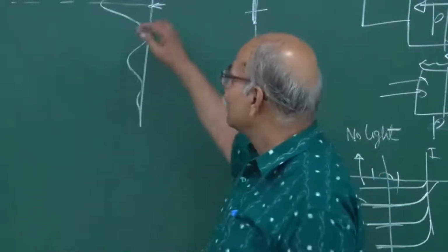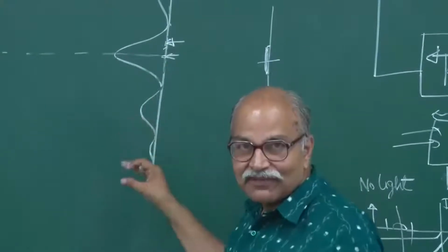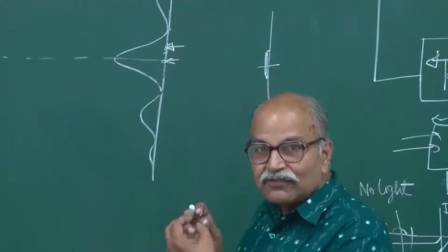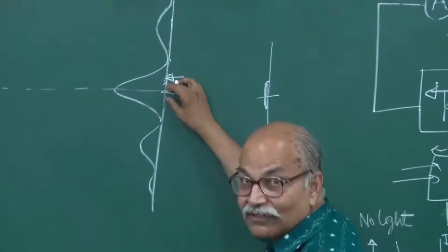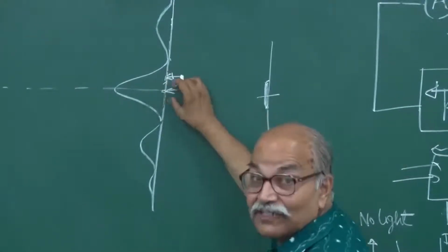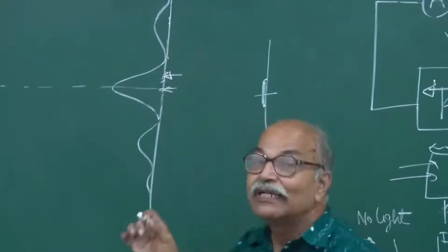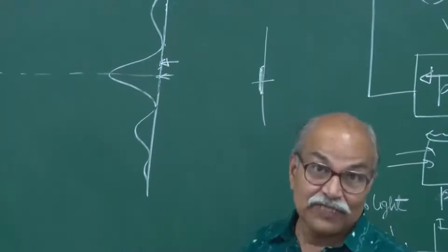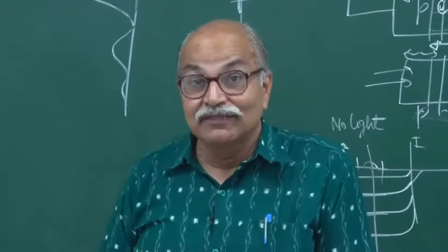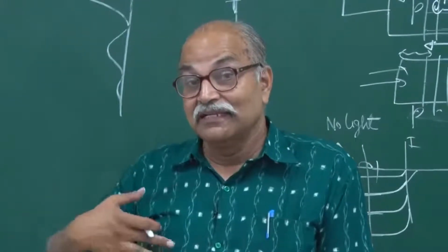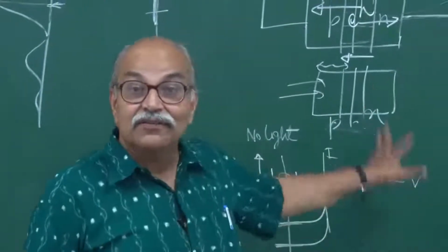Okay, as I said, in the room you will have some background light, so that will affect. Then when it falls on the photodiode, you have to check that it is rightly falling on that. So the orientation of this photodiode, if you shift from here to here and the orientation also changes, then also there could be a problem. Then the photodiode can saturate, so that if the intensity is very high, then it's no more proportional. So that can also create problems.